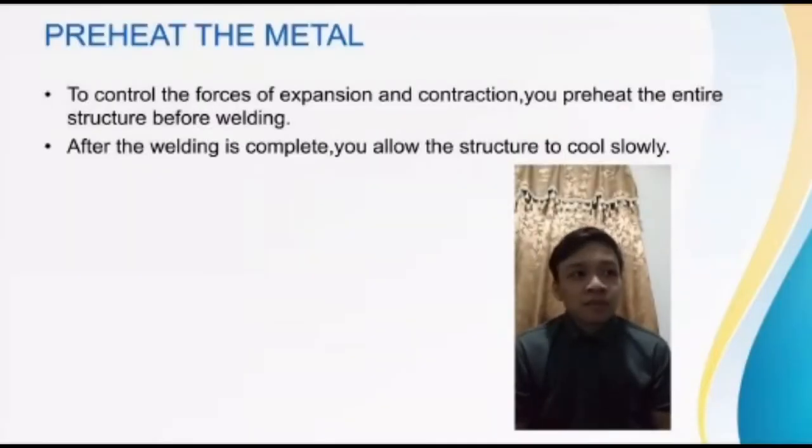And thirdly, preheat the metal. To control the forces of expansion and contraction, you preheat the entire structure before welding. After the welding is complete, you allow the structure to cool slowly.